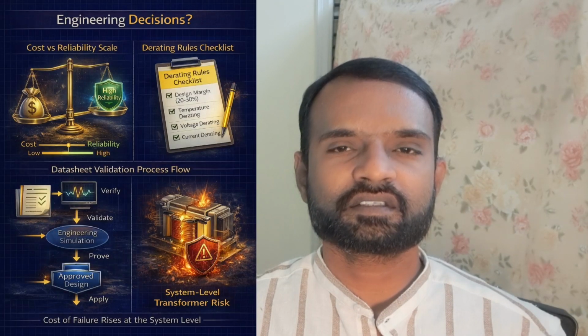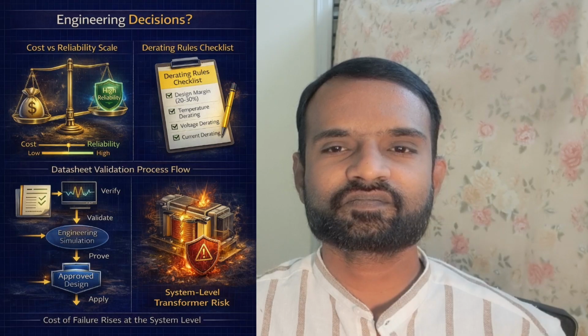Marginal voltage rating. What is meant by marginal voltage rating? It reduces the lifetime and reliability. Always derate capacitor voltage by 30 to 50%.